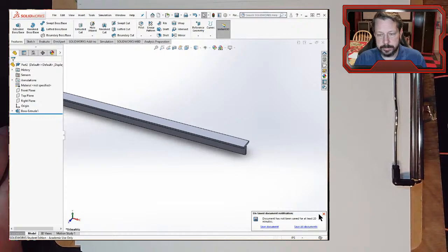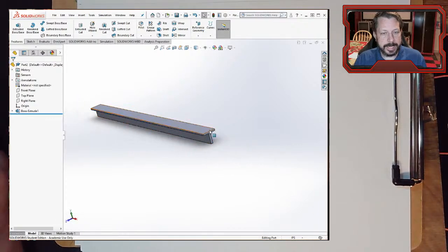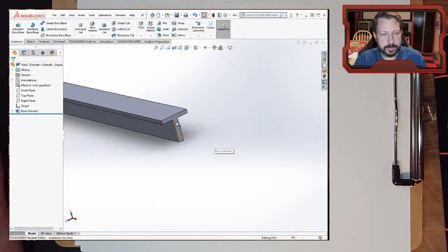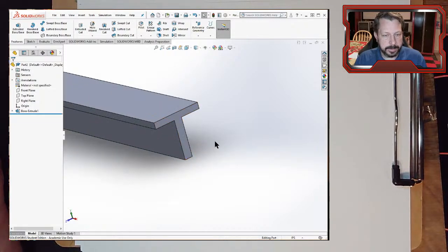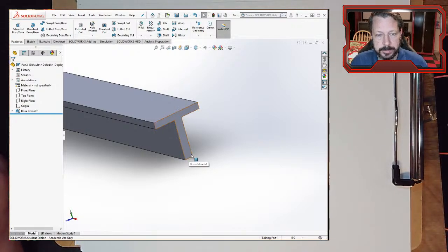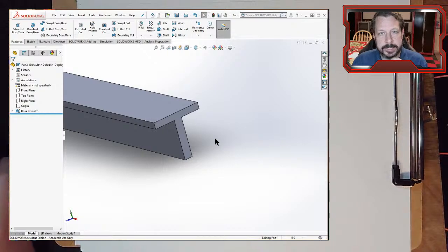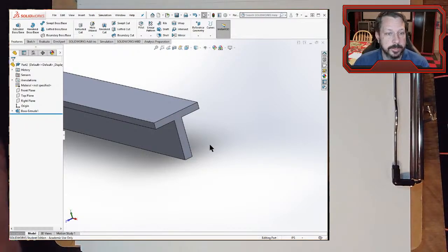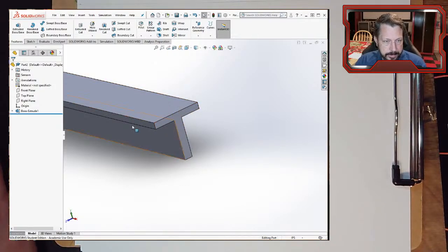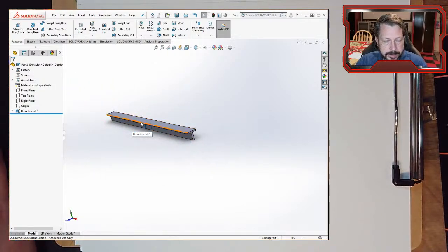Another common shape would be an I-beam. So the end of it, instead of looking like the letter T, would look like a capital letter I. Some are C's or channels, and they look like a capital letter C. There are right angle beams that look like an L. There are all different kinds of shapes of beams. This is one of the relatively common ones. Probably an I-beam, the one that looks like a capital letter I, is the most common kind of beam, other than maybe just a rectangular piece of 2x4 or whatever. But anyway, here's our beam. It's got some length to it.